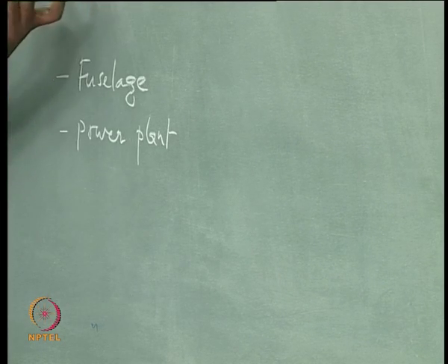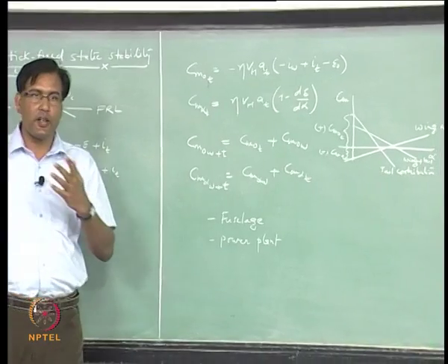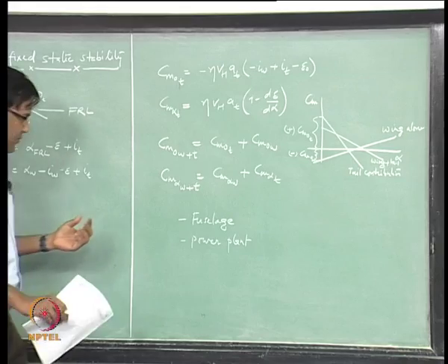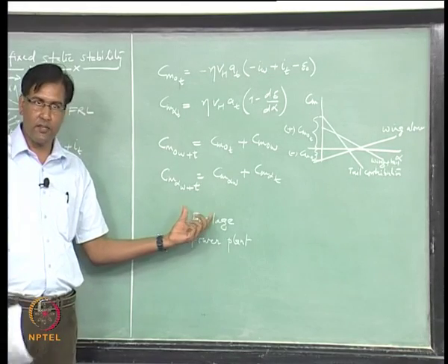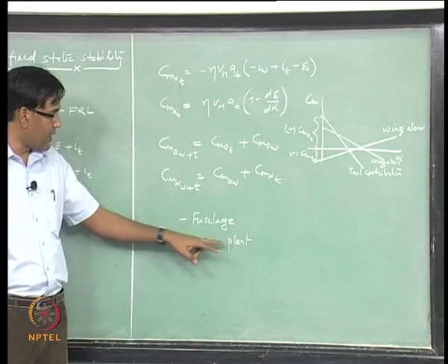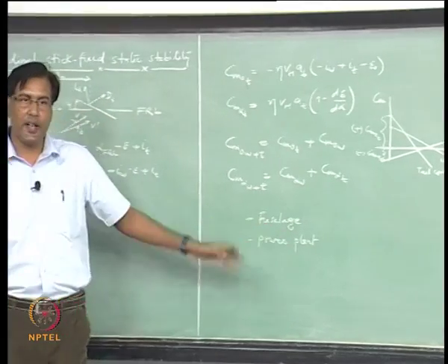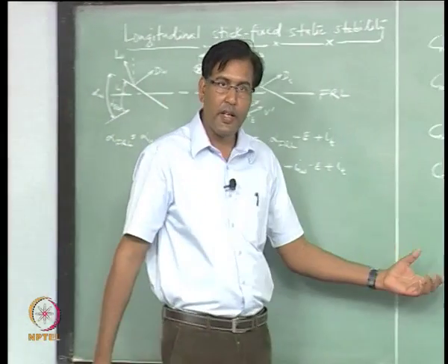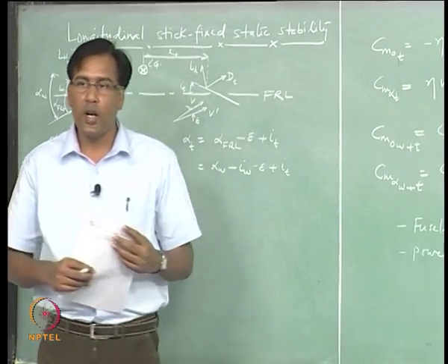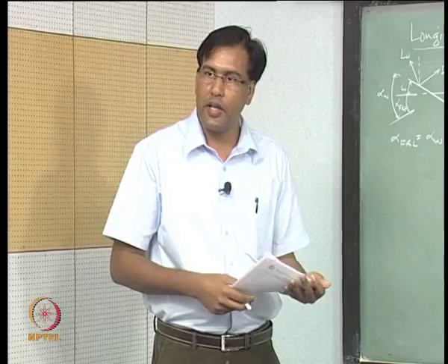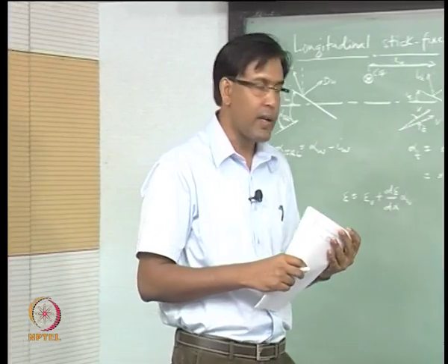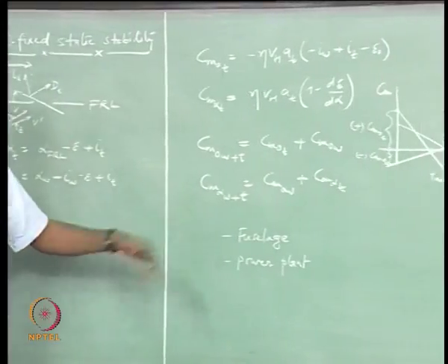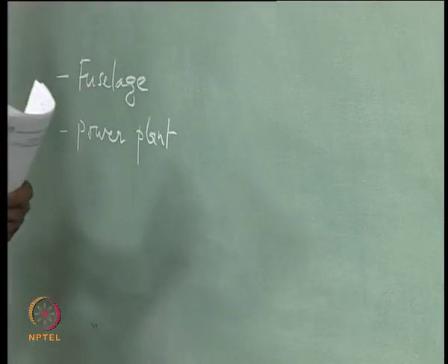Fuselage contribution to Cm alpha is usually destabilizing. I will cover that aspect in the next lecture, and power effects are actually very prominent, okay. That also we will discuss with respect to what kind of power plant you have, right. You can have jet engines, you can have turboprops, right. So, we will look at all that in the next lectures.